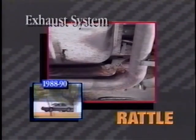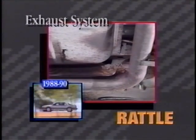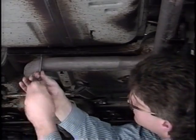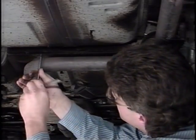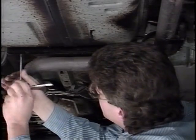A similar metallic rattling noise may also be caused by loose exhaust system heat shields. To eliminate this rattle, ensure there is adequate clearance between the shields, the underbody, and the exhaust. Heat shield support fasteners should be securely tightened using thread locking compound.